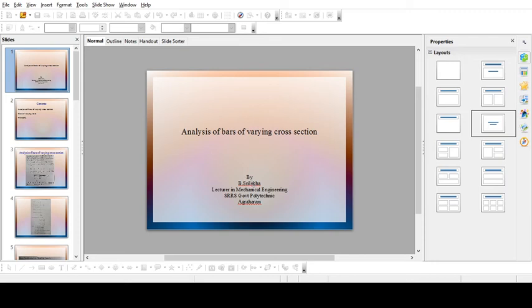Just substituted the values there. Now d value is simply 29.28. So diameter of this portion d1 is equal to 29.28. We know that diameter of both ends is 50 mm. Now area of that end is pi d square by 4, nothing but 1962.